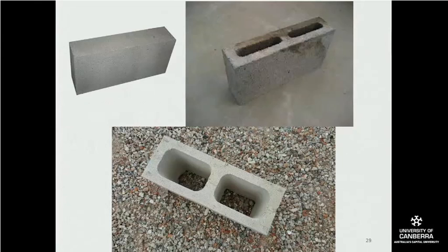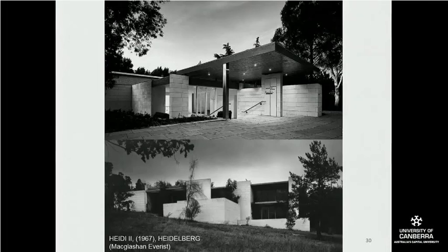This is what they look like. You can actually get solid ones, but most of the ones that you get are hollow like this, with the wider versions having bigger holes in them. These do not require cooking. Like any cement product, you mix up your concrete, you put it in a mold, and you wait for it to dry, and after a certain amount of time, it reaches its maximum compressive strength, as per the lecture on concrete. It's mostly used as a building material for domestic architecture.